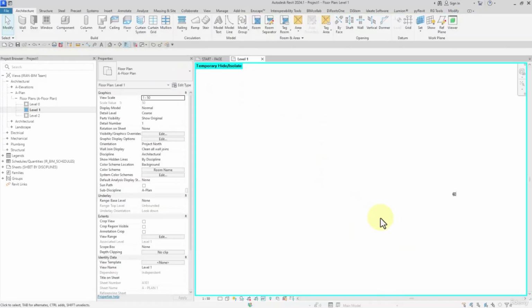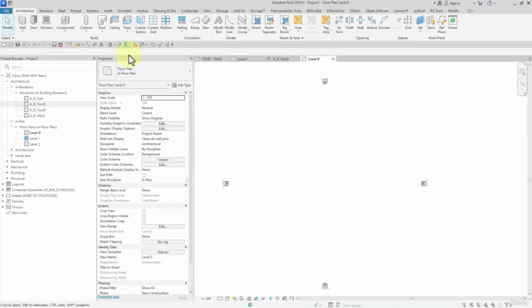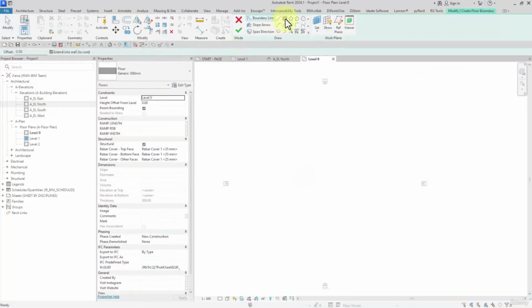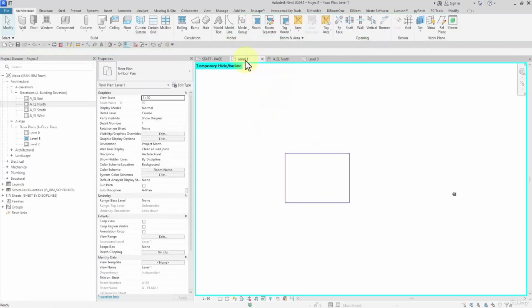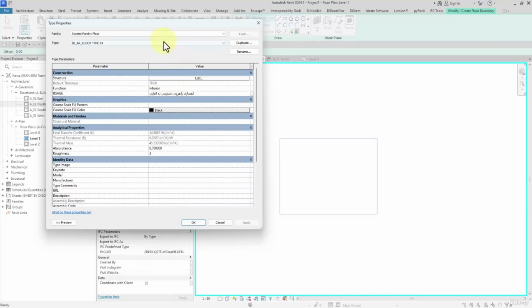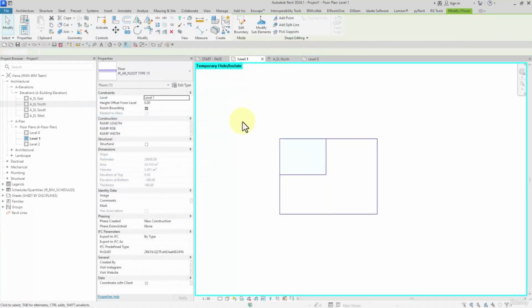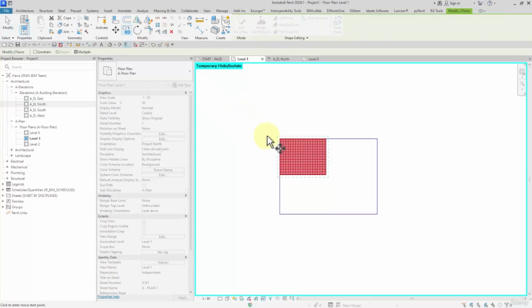For instance, as you remember, we even used the floors in the practices, and also we divided the structural and floor plans. Floor structural, rectangle, watch this, for the slab. Then I open the floor plan, then I can use the finishing floors. So they're gonna have their correct functions, that we will talk about in the continuation about how to create them. But right now I just wanted to give you some explanations.